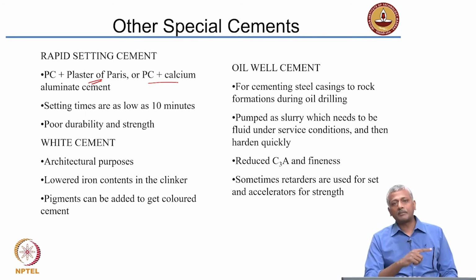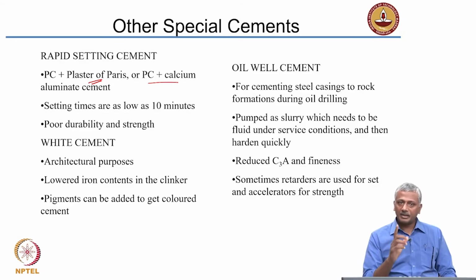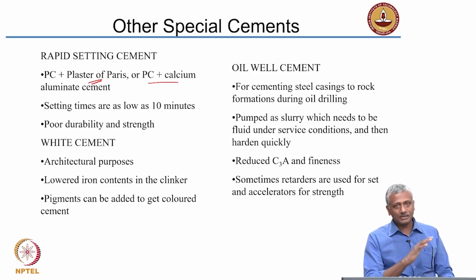We talked earlier about rapid hardening cement or high early strength cement. Those cements are formulated to develop strength at an early age, but they are not necessarily rapid setting. They set normally, but they can get strength at an early age. Here we are talking about rapid setting.